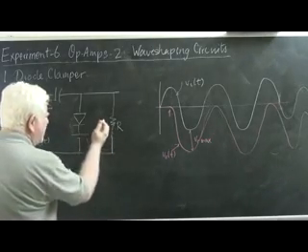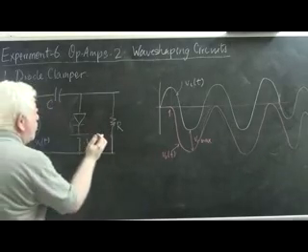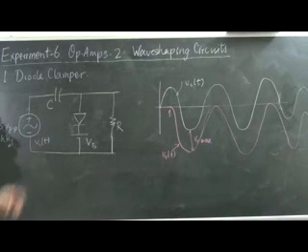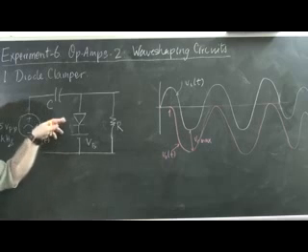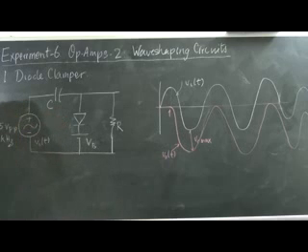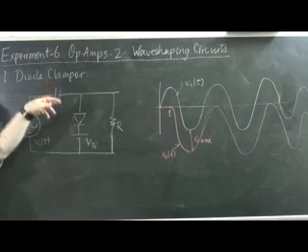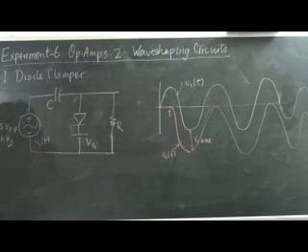Now if we have a non-zero battery voltage over here, what that would do essentially, depending upon the polarity of the battery and the magnitude of the battery voltage, would be to further bias the turn-on time of this diode either positively or negatively. If you set it at a positive value, the turn-on voltage would be shifted upwards.